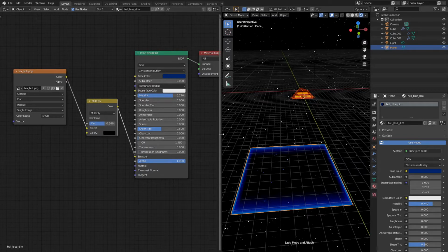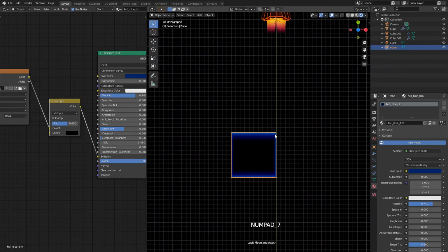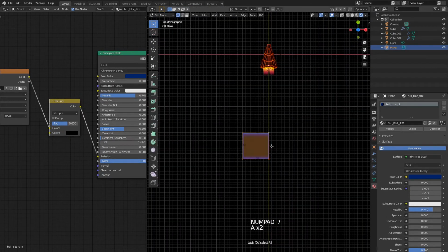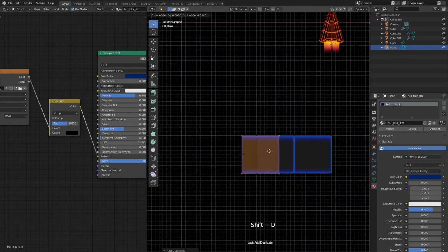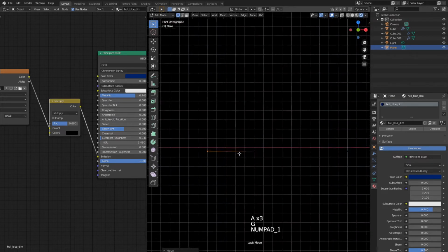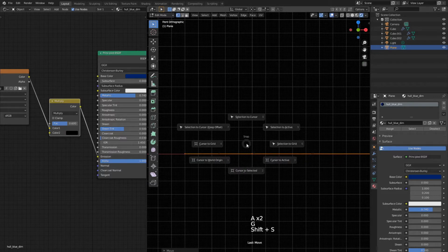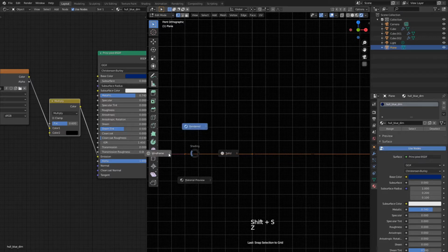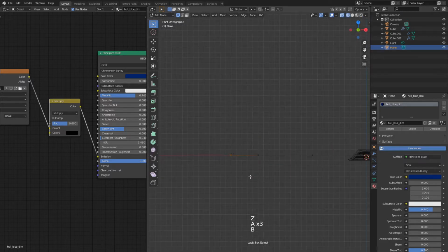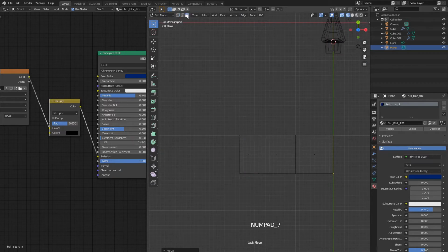Finally we can start building the scene our spaceship will fly through. Now duplicate this square a few times to create the first row of our runway. Two squares will be at floor level. Resize the third square to be half wide. Switch to front orthographic view and make sure our row of squares goes at 0 coordinate on the Z axis. Snap all vertices to grid just to be sure. Now take the left edge of that half-wide square and move it up about 10 units. That's right, we've just created a border around our runway.